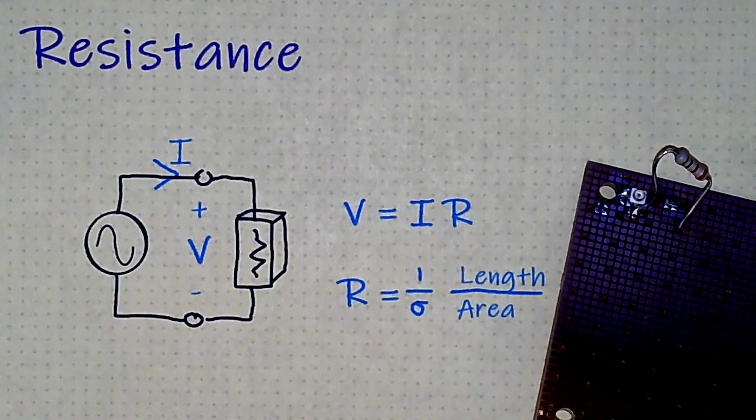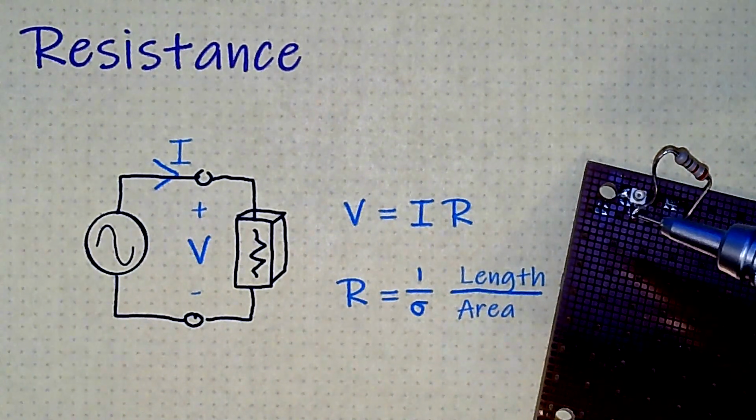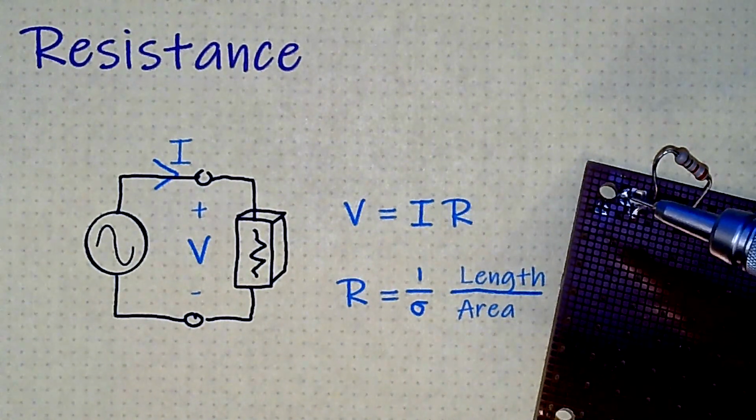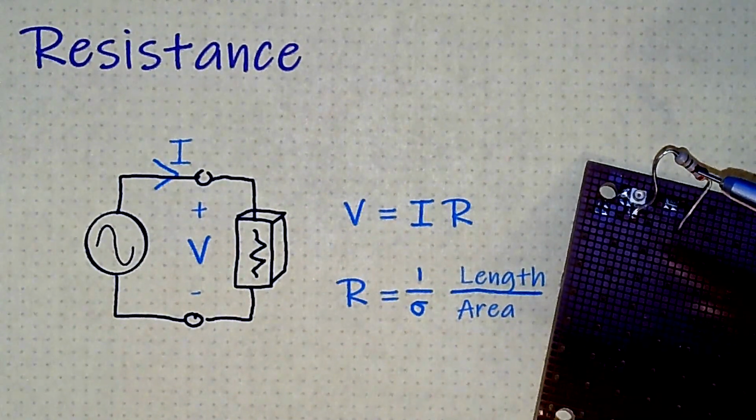So now let's talk about resistors at radio frequencies, and let's measure it with the NanoVNA. Here I have a 22 ohm resistor, and one side is attached to the center pin of this UFL connector. UFL connector ground goes to the back side of this board, which is a copper ground plane, and then the other side of the resistor goes through a via hole to that backside ground plane. So we're going to measure this, and what you're going to see is that this is not just a 22 ohm resistor once you get above, say, 100 megahertz.